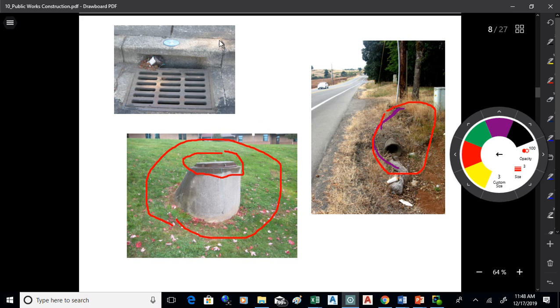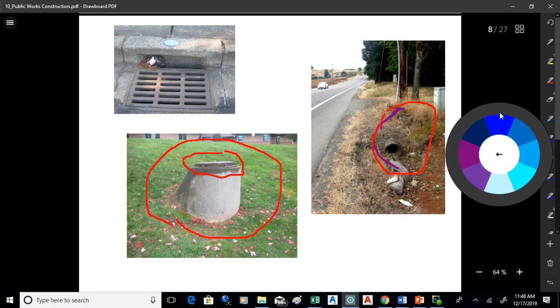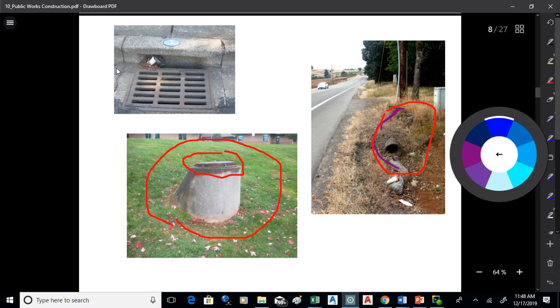And then this particular one is a catch basin, where I have a grate that will lead the water down into this box. That's a concrete box, and there's a pipe running out of the box that would then go to the manhole. A catch basin has a grate on the level of the gutter; with a curb inlet, the water enters through the curb. So this one's kind of a combination catch basin and curb inlet from the look of it.